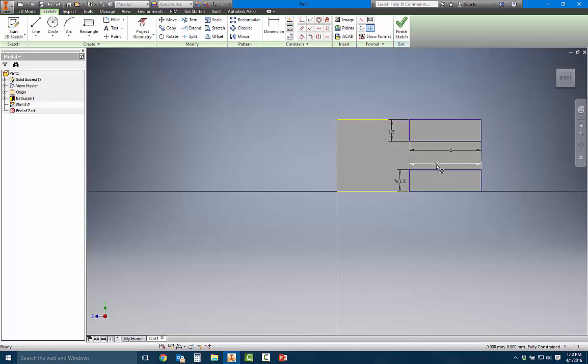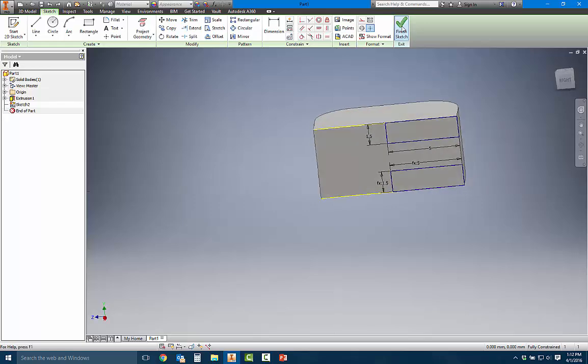And we can also do things like, what's really cool is I could do something like, I want it to be as big as this dimension divided by 2, which makes it half. Right? So there's all kinds of cool stuff. That makes it really easy to have one set of parameters that control the geometry of the whole object by their mathematical relationships, which makes it really easy to resize things and stuff like that if they have some kind of nice constraint relationship. All right, so there's that guy. So that's the end of this sketch. We're going to finish that.